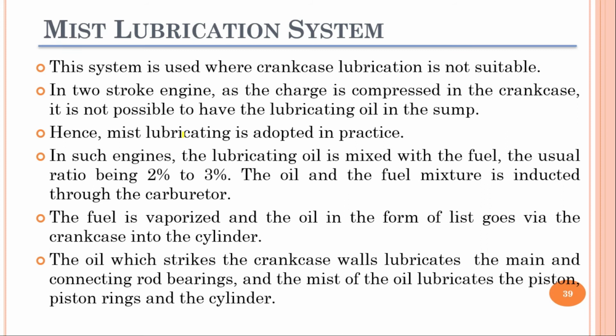These lubrication systems are generally used in a two-stroke engine, and in two-stroke engines, we cannot have a crankcase lubrication system because compression is being done inside the crankcase. So what we do is we basically mix the oil with the gasoline.